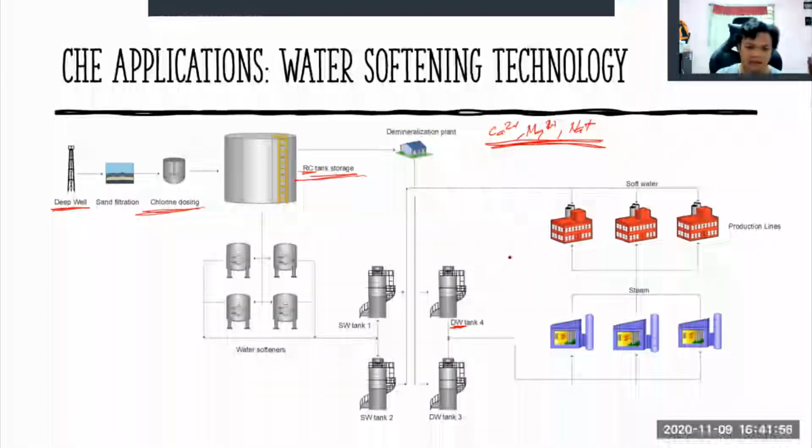Right. And then we have also the second part, the water softeners. Water softeners just remove these two. They do not really remove all minerals in water, but they remove the hardness of water, so calcium and magnesium, and they usually use ion exchange technology for this.